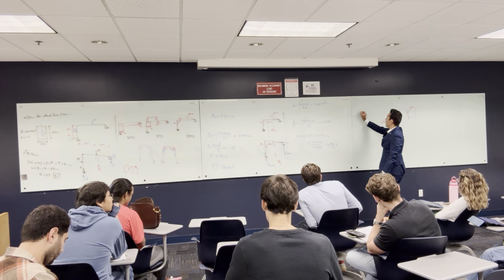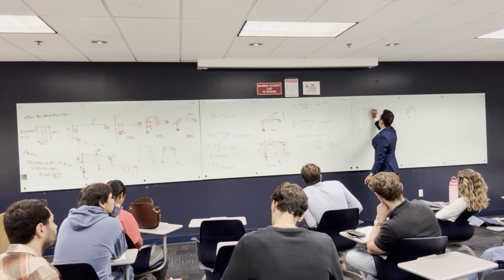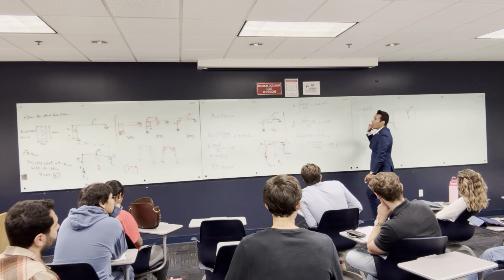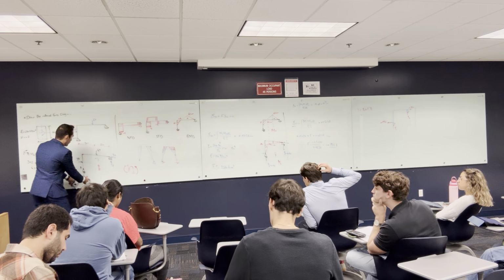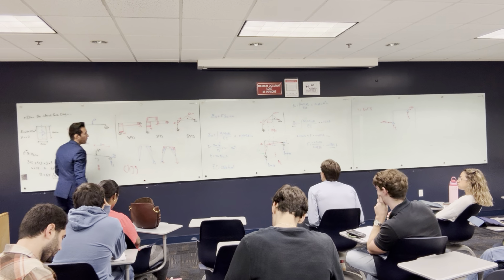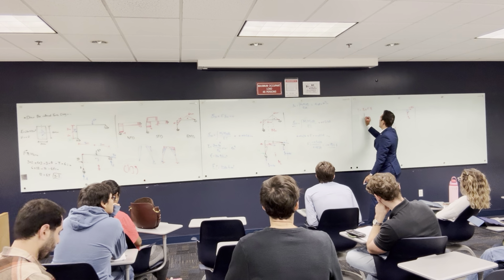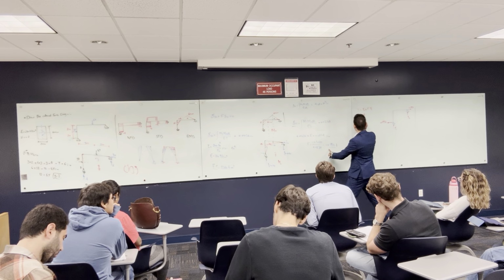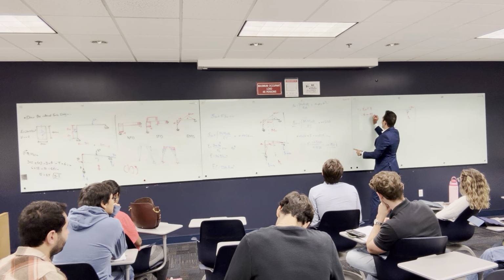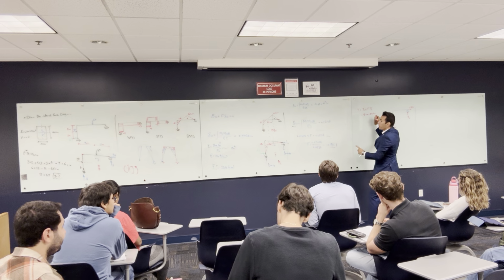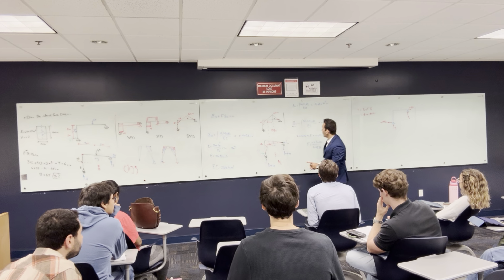If you want to find the value of these two reactions, let's say this is Y1 and this is Y2. Y1 should be equal to YO plus F multiplied by Y1. YO is the reaction from the main system, this one, the 4. So I'm going to put this as 4, plus F, which is negative 0.452, multiplied by Y1, the reaction that comes from this system, which is 0.67.